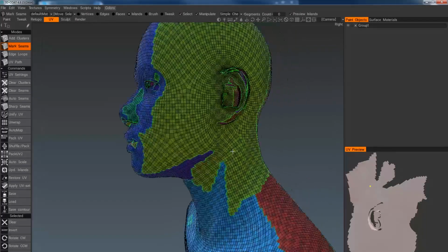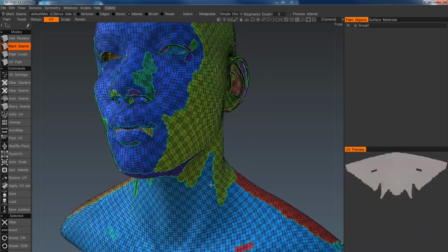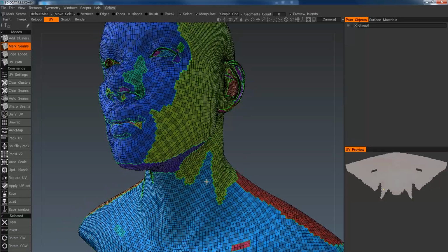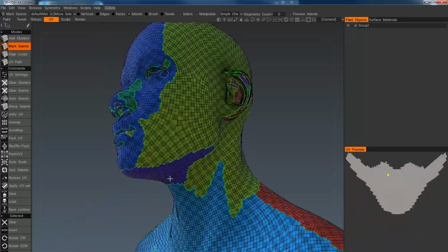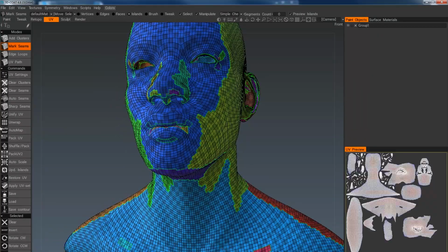It's really doing something really terrible. If it was a simple object like a box or a cup, it would do the job for you perfectly fine. You won't have to cut any UV at all. But this is really complicated for 3D Coat to do. So let's unwrap this so that it can bake it into the mesh.